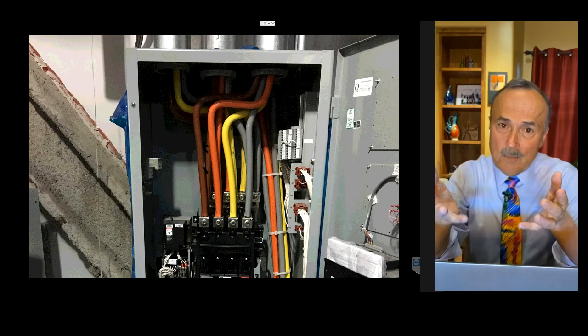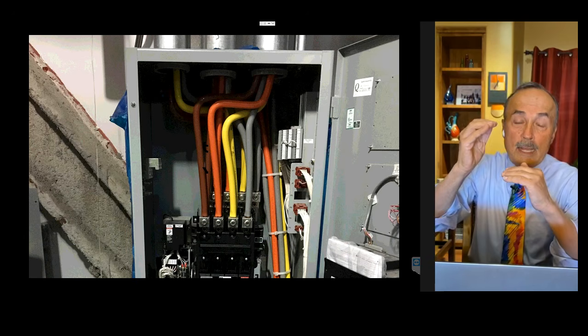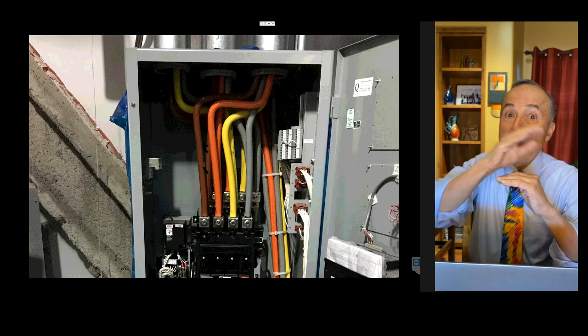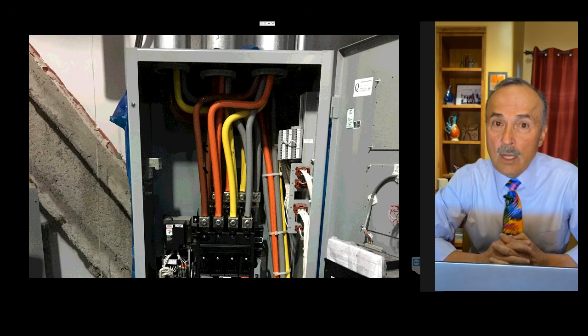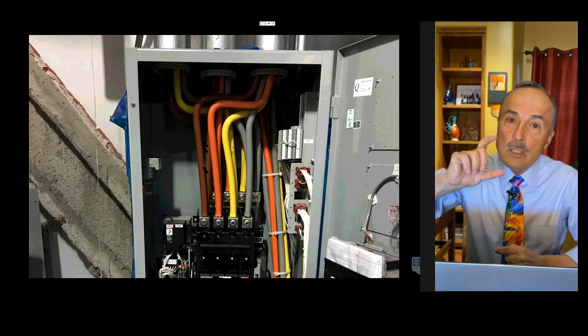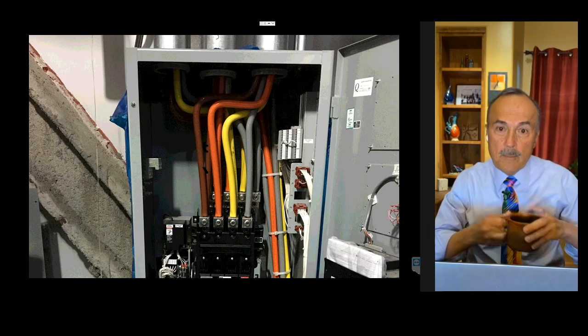Pretty much this is done by the manufacturers, but there are times that you might be installing a terminal and you have to make sure you have enough space to bend the conductors. But 312.6(A) is not talking about the radius of the conductor bends. It's talking about the distance of the terminals to the enclosure. So no. Anything else?